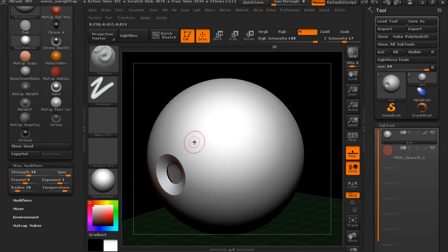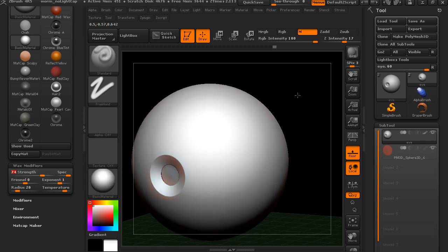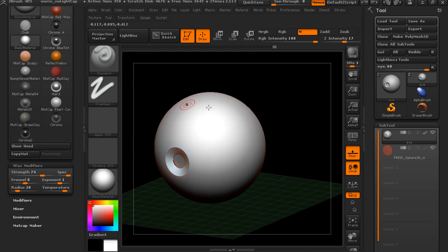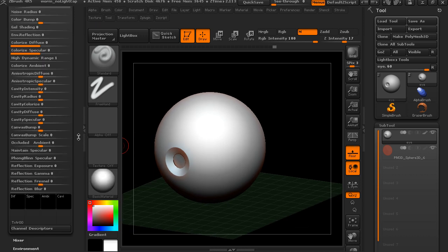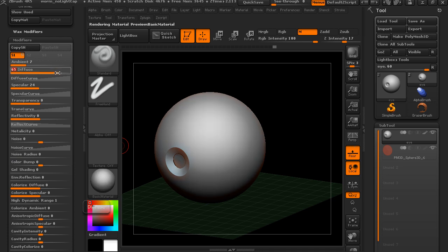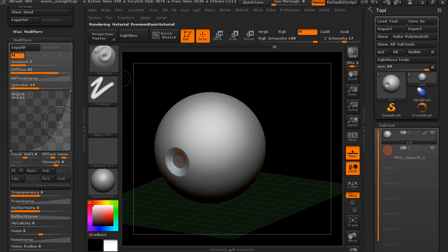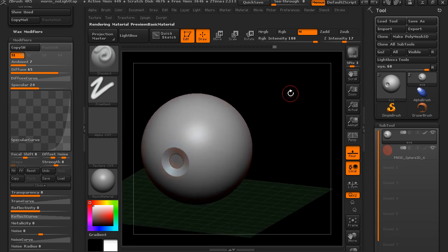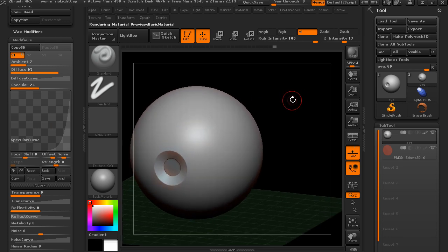You can see there's a subsurfacey kind of a look there where if I increase that strength, you get a glow or subsurface glow, and you can take your diffuse down a little bit, make that maybe a little bit more apparent. Maybe take your specular up and increase the shininess a little bit. And you get almost a skin type look starting to happen there with that wax preview.